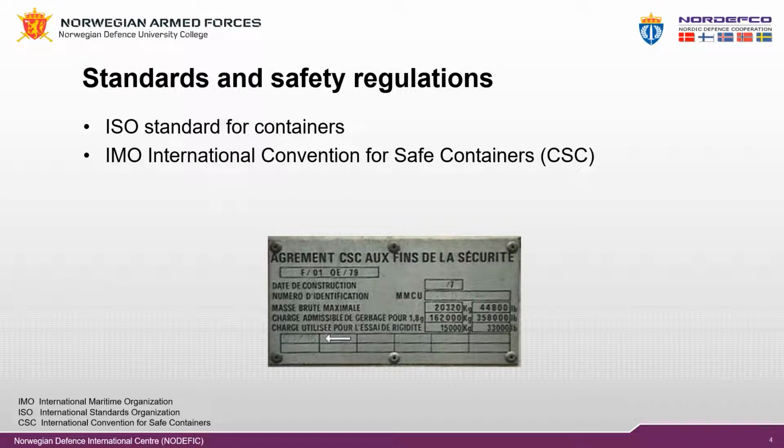The original safety certificate is issued by the container manufacturer. However, once the container is under ownership, the owners are responsible for the safety certificate renewal. The renewal takes place by a certified inspector after 5 years initially, and then every 30 months thereafter.